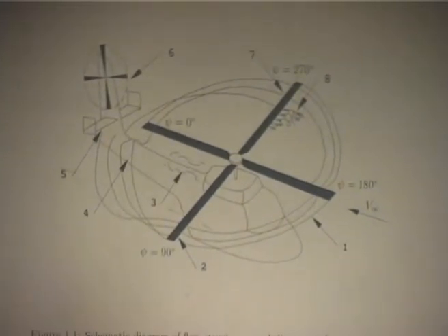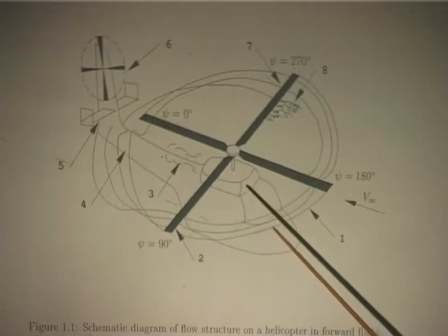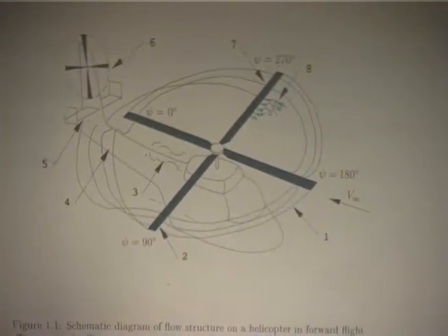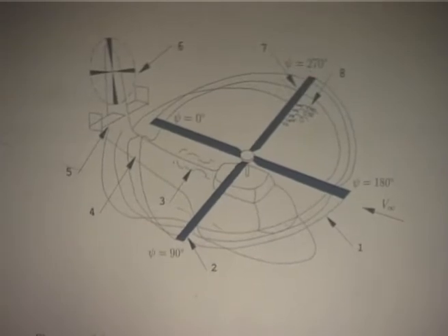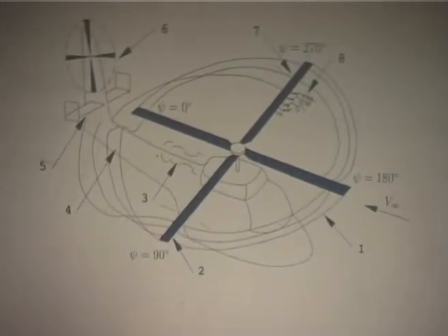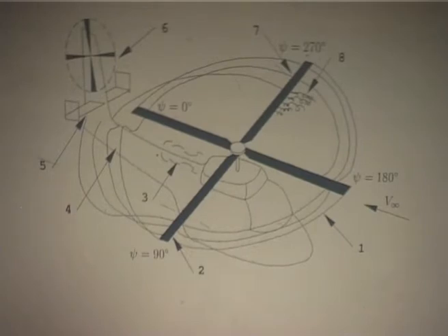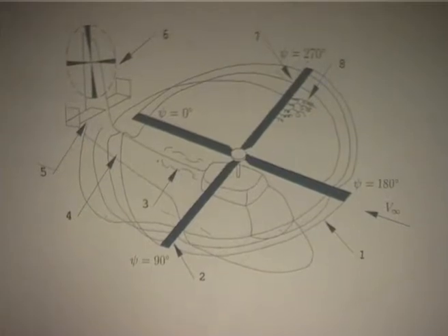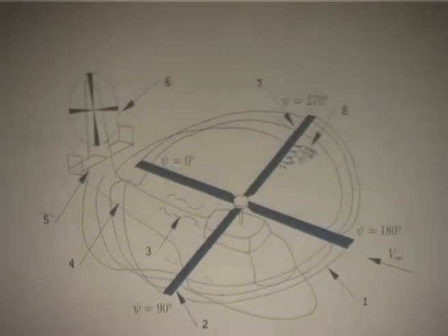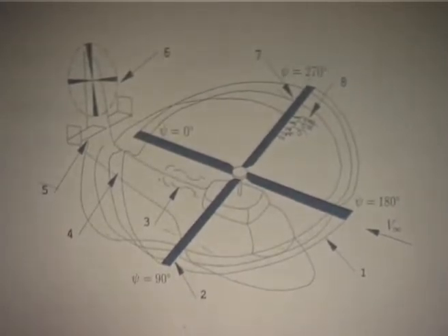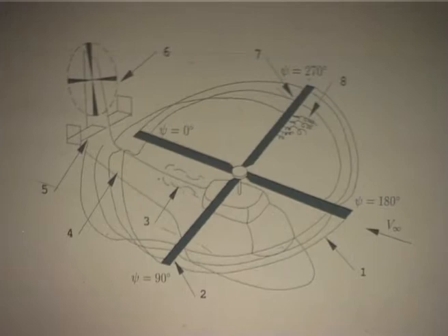And the wake, basically the disturbance from the rotor and the fuselage, they hit the airframe, and then the wake and the tail will interact. So, you will have all sorts of aerodynamic complexities, please understand. Now, you can't treat everything even today, okay. So, what do people do in industry? Of course, the work is still going on, people will keep on doing it. It is a very, very complex structural dynamic, aerodynamic interaction problem, okay. We will make it highly simplified, okay.